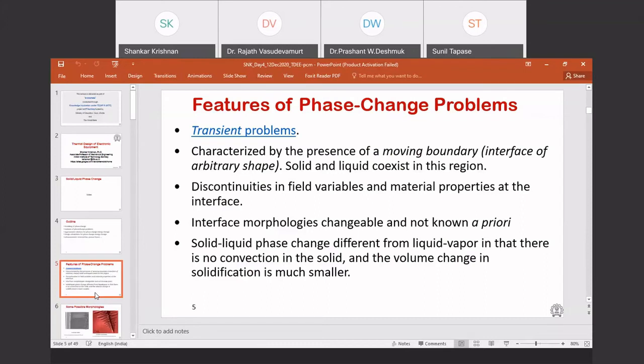So we proposed to use phase change materials to absorb that transient pulse. Otherwise, you have to create such a big volume heatsink, because you have to design the heatsink for the higher power that is happening over a shorter duration. So that is unwanted sizing of the heatsink, weight increase, and so on. So phase change material offer a very nice solution in this case to absorb that transient pulse, because you don't keep starting your motor every 10 minutes.